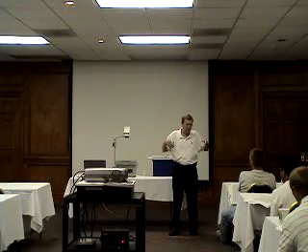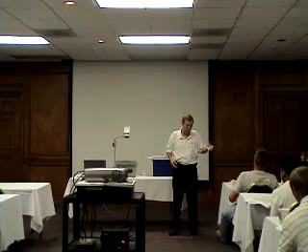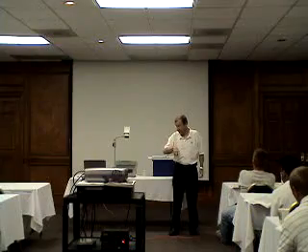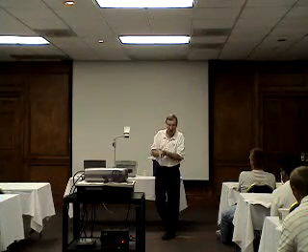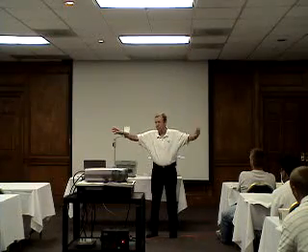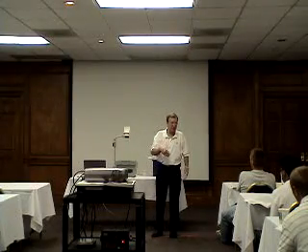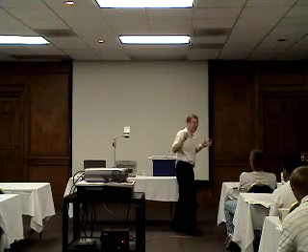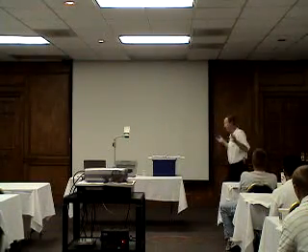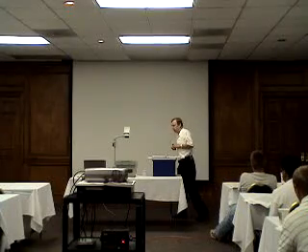You know, maybe yesterday you said something I didn't think very much of. This morning I pulled that first truck over, just to keep that kind of stuff from happening. You follow the procedure. There's no ifs or buts to it. The sample must be taken from wherever this procedure says, and the technician can't vary it, or he's in violation of the spec if he does.